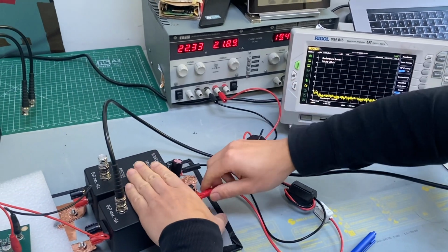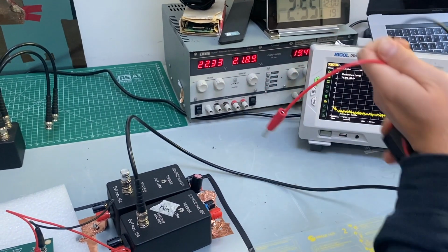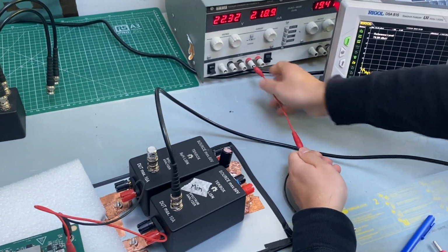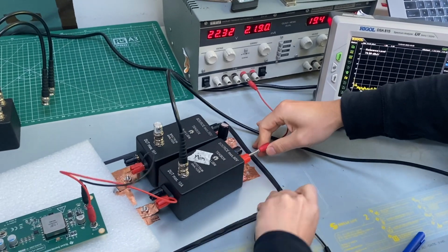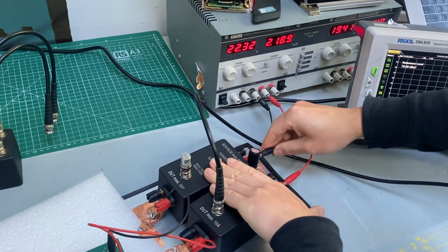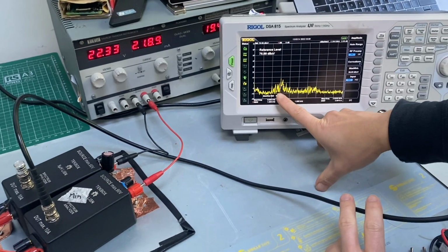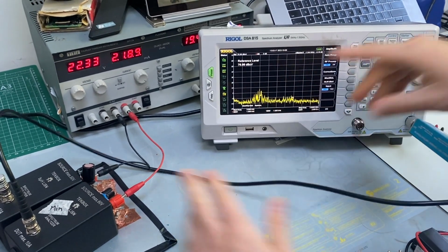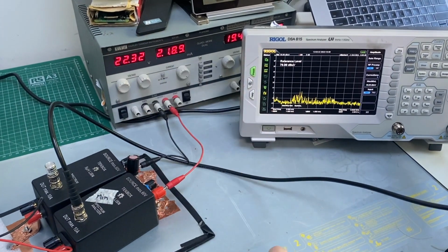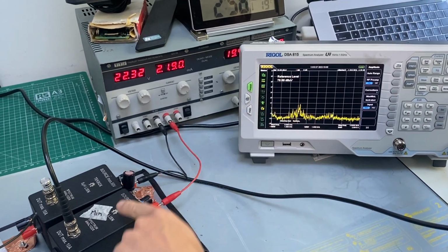Now, what I'm going to do is disconnect this connection and replace it with a normal wire connection, okay? So I'm connecting here directly to my LISN, and here directly to my LISN, right? Simple like that. And check out here. You can see there is noise immediately picked up by the LISN, and I'm not even turning on the power supply unit yet. We already see noise measured on the LISN.